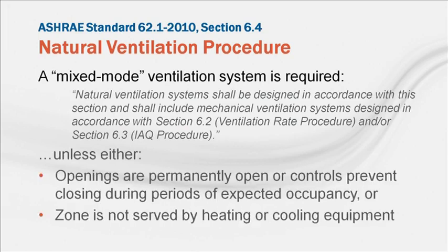Now there are a few exceptions. For example, if the openings are permanent and not able to be closed, or if they're automatically controlled and those controls prevent the openings from closing during any occupied periods, then a separate mechanical ventilation system would not be required.